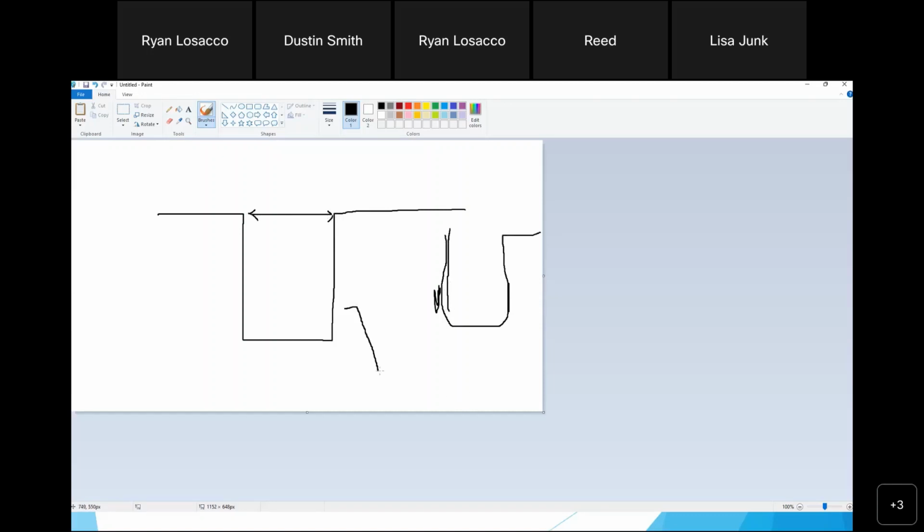Now, if we have a dramatic draft angle, that's nice because then we can see what our smallest diameter is down at the bottom because nothing's blocking our view. So that's a little tricky. Where do we want to take the measurement? And using those different Z heights that I was telling you about, if we know how far that blind hole is supposed to go down, you can right click, move down that blind hole height, and you should be able to see that